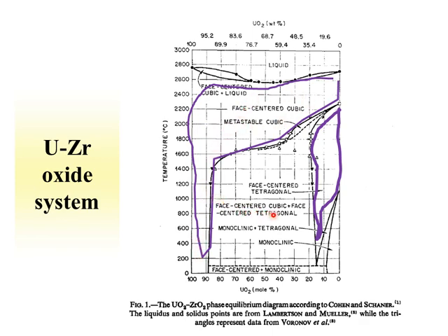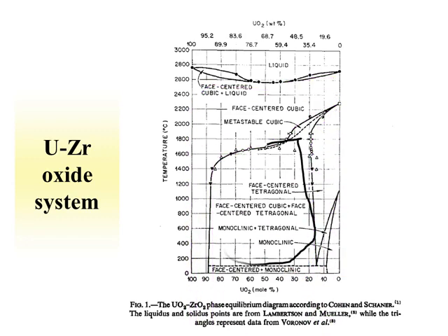When we got to higher and higher amounts of zirconium, obviously more than you would see in nuclear fuel, you would have this face-centered tetragonal form dominating. You'd have a mixed phase here and then a monoclinic form here. Within this regime, at lower temperatures, we have two species formed. Now, in this regime shown here, we have multiple phases formed, face-centered cubic and face-centered tetragonal. So when we started to reach percentages of uranium that were lower than what's shown outside of this solid solution regime, we start having mixed species.